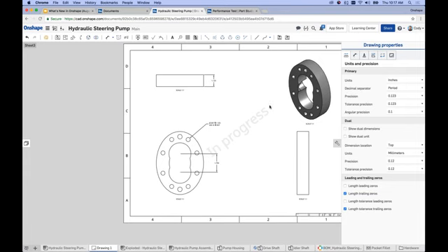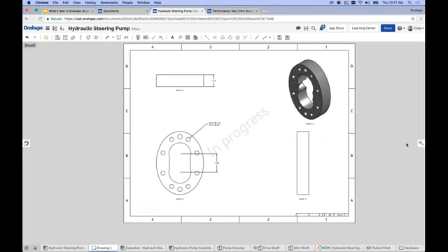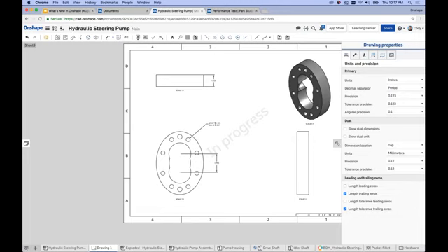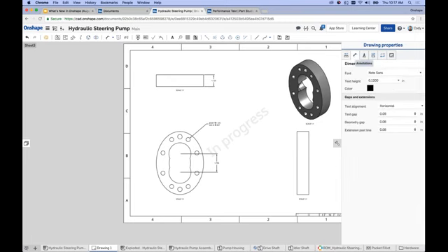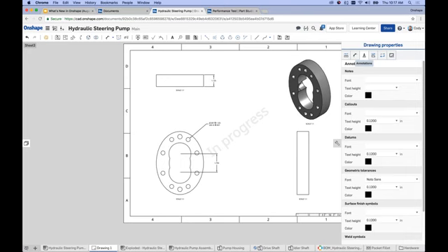All right, so that is the drawing properties flyout. Now, the flyout itself is new. Again, this wrench icon is how you access it. It's on the right-hand side. That's how you fly out, and you see all the various tabs with all the various pieces of functionality. There are a lot of new bits of functionality introduced with this new flyout. Things like the ability to adjust dimensions and annotations, the fonts independently of one another. That was a limitation in the past. That's no longer the case. You can adjust those independently.